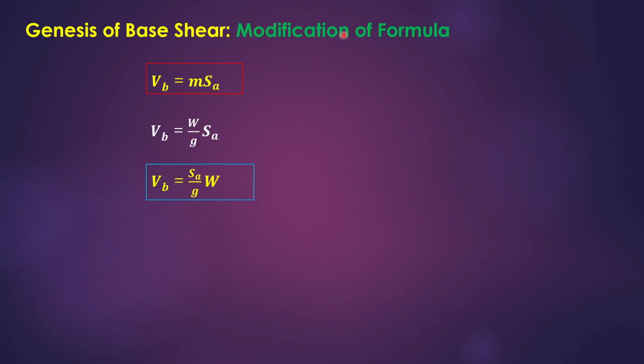One modification is the introduction of the different areas, which we take up with the help of the zone factor. As we have discussed earlier, there are zone factors associated with 4 zones in Indian seismic conditions. In other countries, this is considered with respect to zones or seismic contour lines.